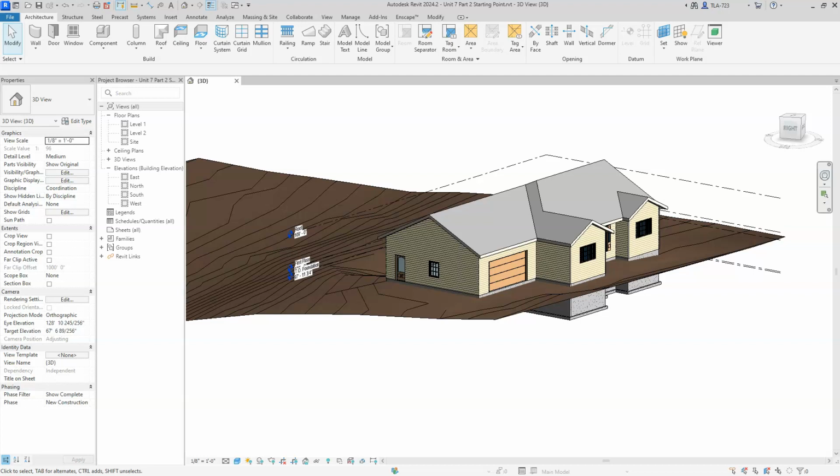All right, we left off on part one right about here. And in part one, we learned about how to create a topography from a CAD file. So you can create the CAD file first if you want to, and then just pull that into Revit. We learned that. We also talked about how to link projects together. And this is something that's really important. We do this all the time, cross disciplines.